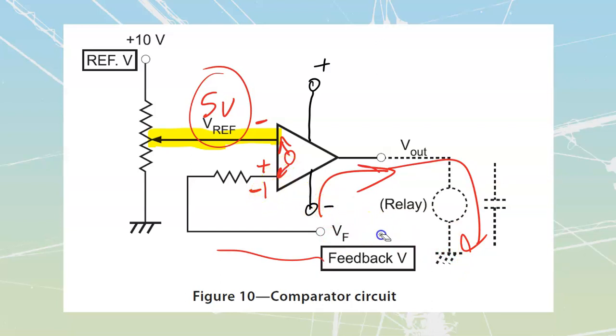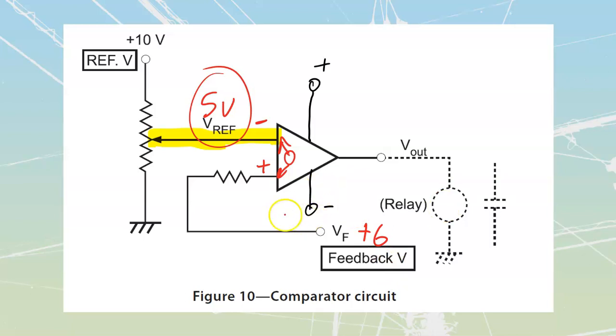However, if I bring this value of voltage up, let's take this value now to plus 6 volts over here. So I'm getting 6 volts from my feedback, my tach. EG is equal to VLV, which probably means that we're going faster. That 6 volts is going to be seen as plus 1 volt in reference to this 5 volt. Remember, that's what it's comparing it against. So plus 1 volt in reference to that. The little voltmeter inside of here is reading plus 1.